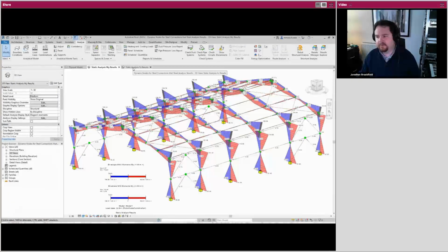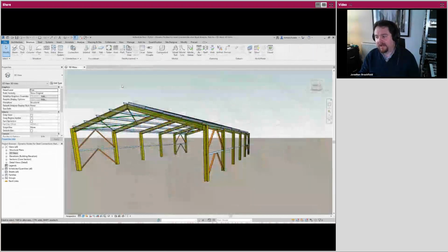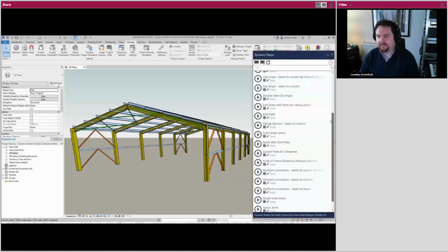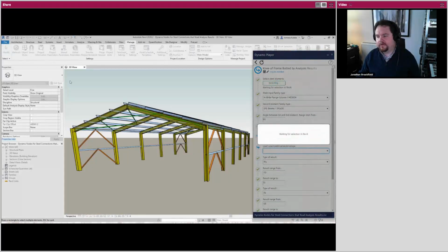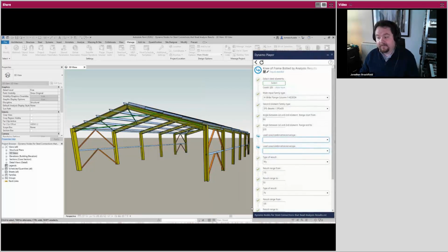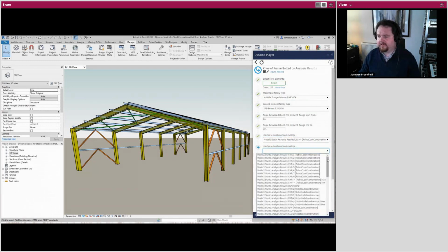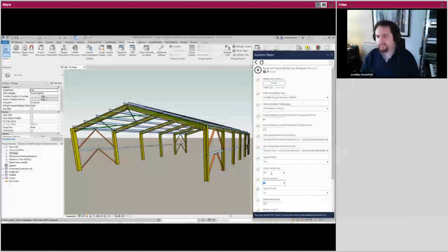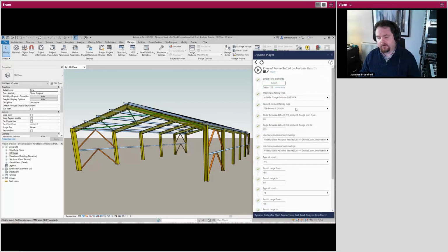The filtering follows a simple rule. The user-selected force or moment type is read from the beam or column end that is part of any given node that is analysed. Then, it is compared to a range of forces or values that are also user set, and if the value fits inside the given range, the rule will continue placing the connection. This functionality to drive steel connections by structural analysis results tightens the integration between analysis and detailing phases, helping you make better design decisions when adding steel connections to structural models.